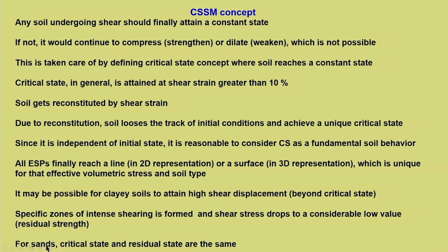For materials like sands, we can notice that the critical state and residual state are the same. For them, such excessive movement is not possible. It is only valid for certain kinds of clays under certain situations. In that case, the residual strength gets invoked. Okay. So, there is some difference between the critical state and the residual strength that we discussed.